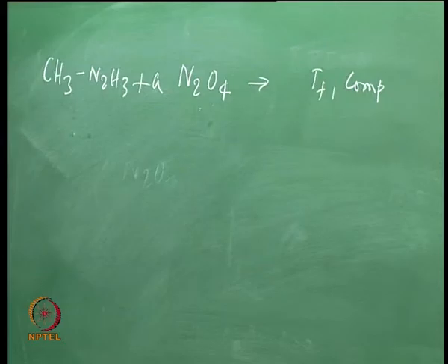Therefore, the procedure is, first we use the hydrogen in the fuel which searches for the oxygen and consumes it. The balance oxygen is now available for carbon to react either fully to carbon dioxide or partially to carbon monoxide, or if even oxygen is not available, to carbon, and the nitrogen in the fuel or oxidizer is available in the products as N2.